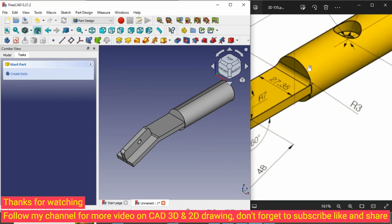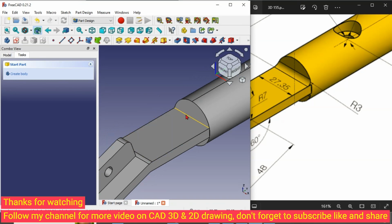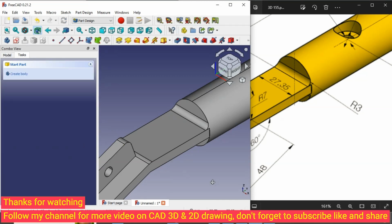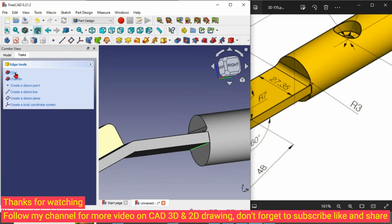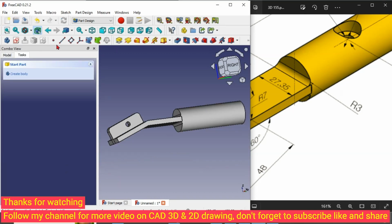Next, we have a fillet here, radius 3 on the upper side and on the bottom side. This is just a simple drawing. Just click here, then click fillet, and we set the radius to be 3. Roll it a little bit for the side. Fillet 3. Okay, done.